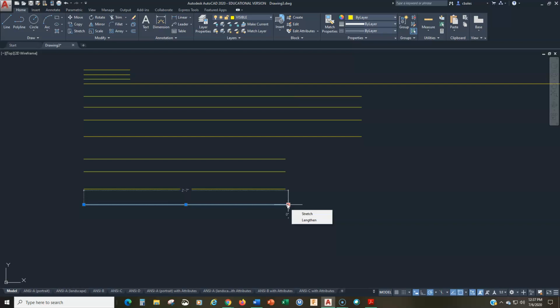I put in 2 foot 6 7/8, and it displays a rounded number, 2 foot 7 inches. Now this is important. The line is drawn completely accurately. It's just this number display on my distance that is basically rounding up. Okay, the line was drawn completely accurately. Okay, so that's a good thing to know.